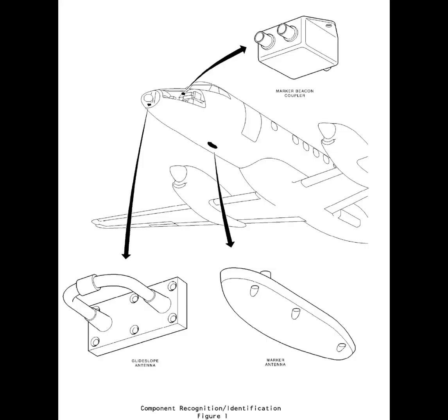Where should antennas be located? Lower surface. Position not blocked by the wings when the aircraft is banked. Why are doublers required to be installed under aircraft skin when an antenna is mounted on the aircraft? Prevent cracking in the skin.